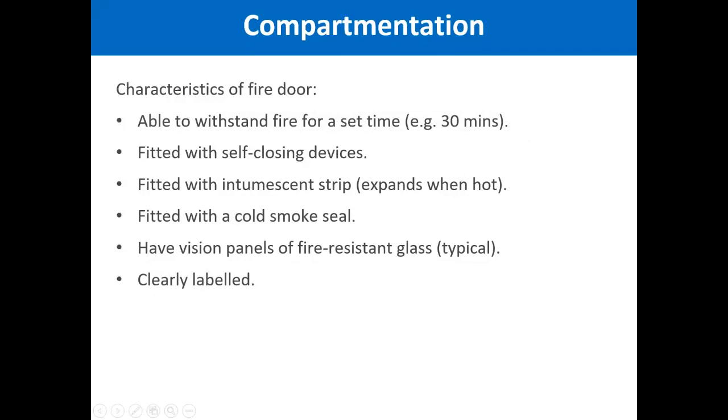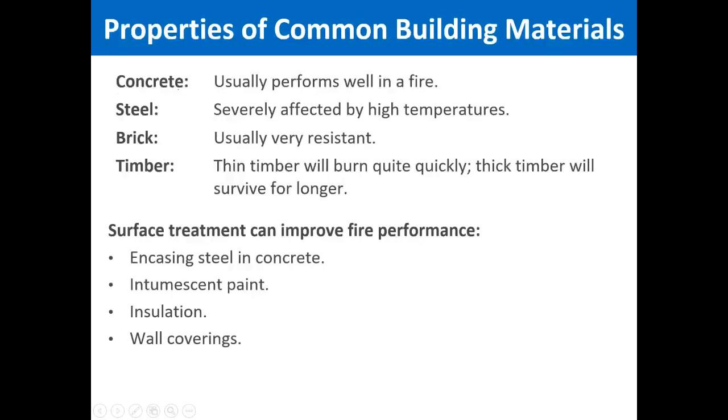Okay, the door of the compartment has certain characteristics as well. It should be able to withstand 30 minutes of fire. It should be fitted with self-closing devices. Intumescent strip should be fitted. Cold smoke seal should be fitted as well. Vision panel should be there. Should be clearly labeled as well.